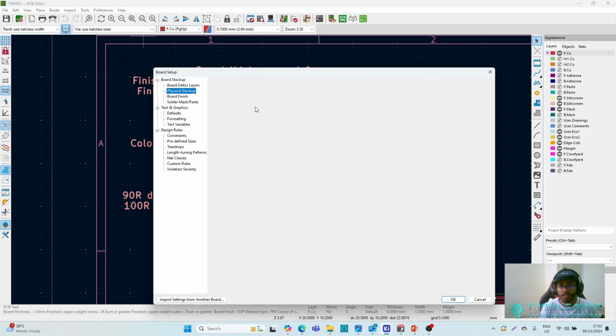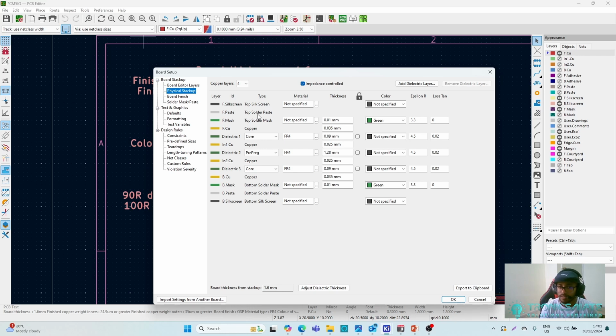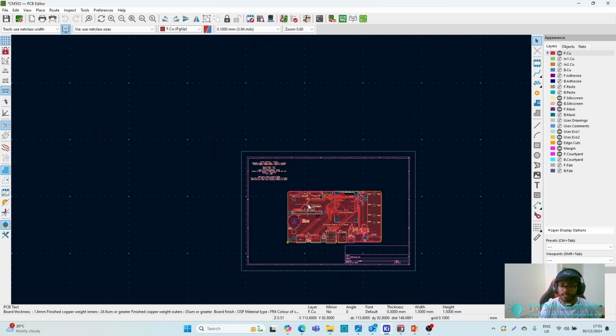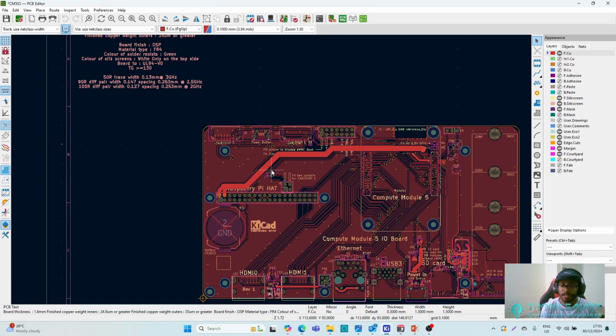It is very important to inform your PCB manufacturer that you need impedance controlled signals and that you have calculated them with these settings. Then the PCB manufacturer will change their stack up, match the impedance, and manufacture the PCB.